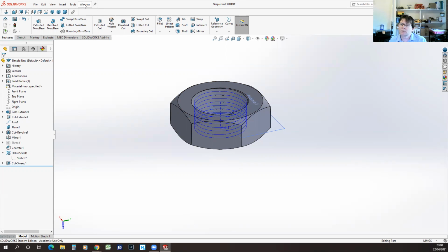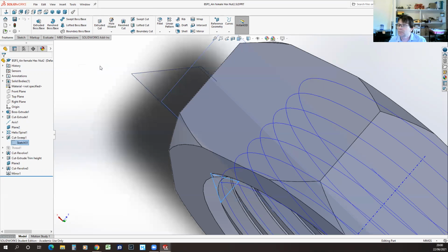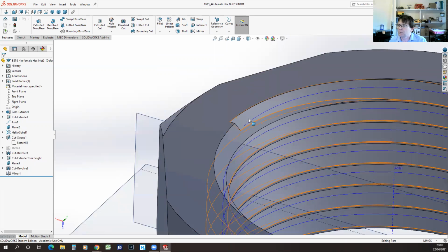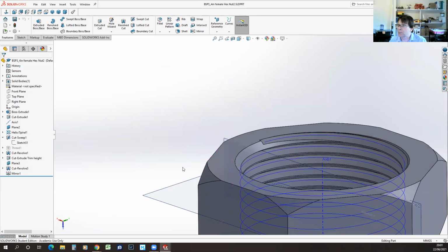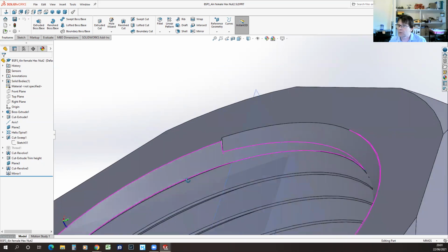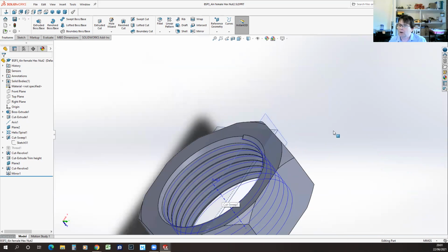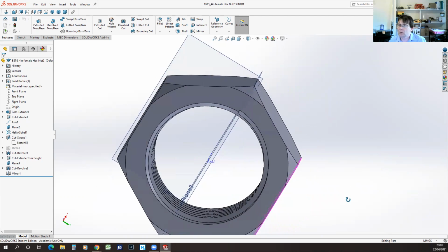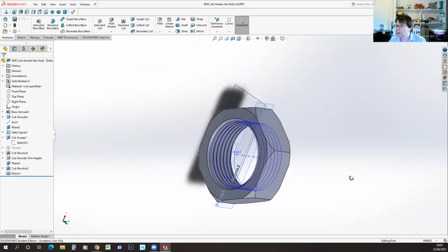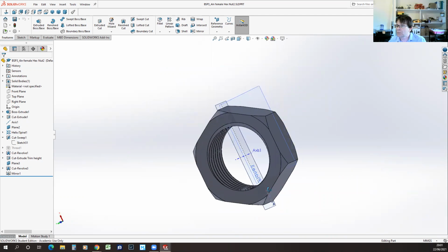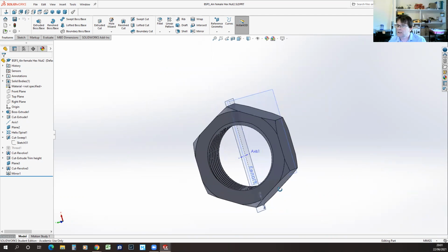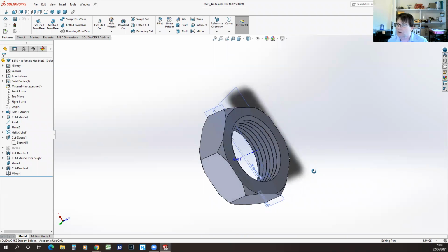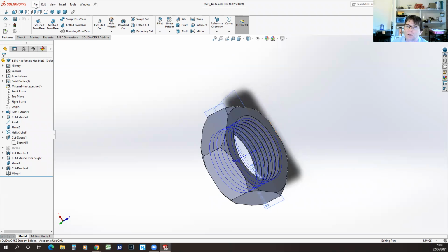Let's switch back to the one I actually 3D printed. You can see that I actually made a kind of bigger chamfer, so you can see where my thread starts to cut in. But at the scale of the 3D print, that was absolutely fine for that thread to go all the way through. And I didn't need to finish the bottom with a chamfer because I actually joined this onto another part, which I can show you.